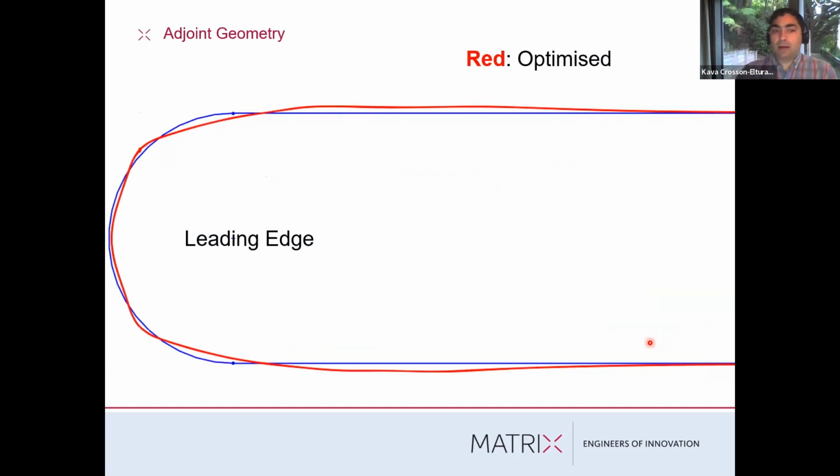So now we're looking at that wrinkly area that we saw on the supporting column. It's a view from above and a cross section. And again, red is the optimized geometry, and blue this time is the original geometry. What I found interesting about this was that you end up with these sharper radii connected by linear or practically linear regions. I found that quite interesting and unintuitive, but it did lead to a substantial reduction in drag, probably because of the suction that was induced on this surface, this forward-facing surface here.